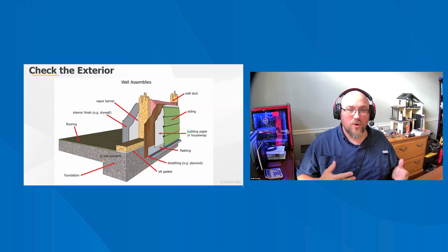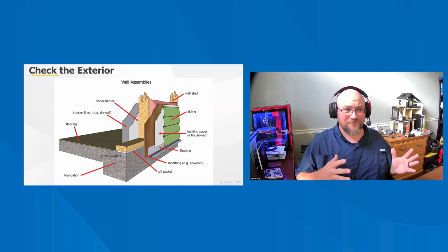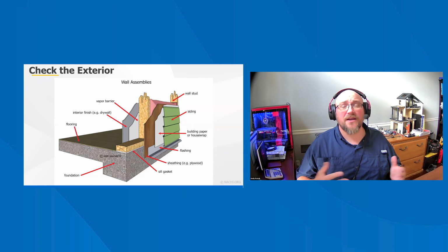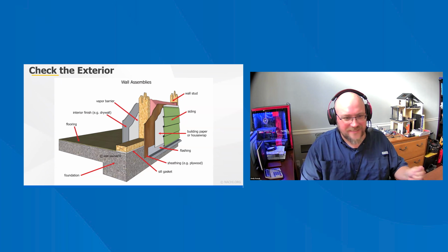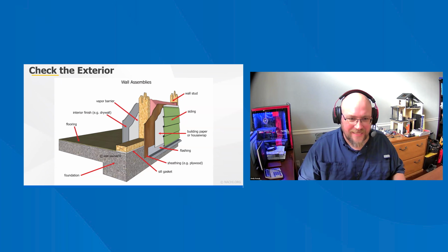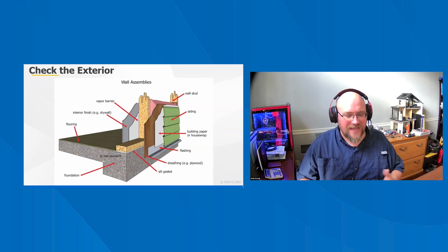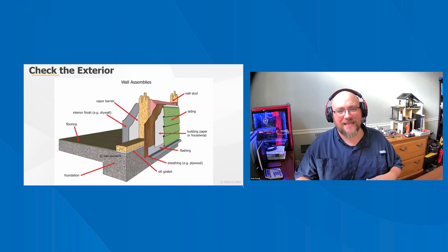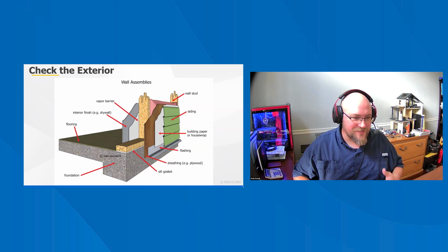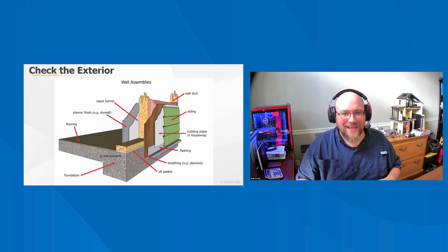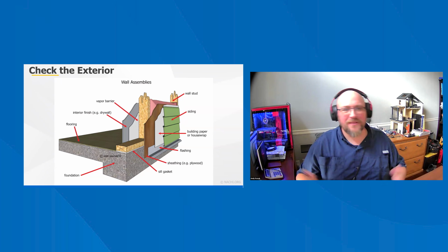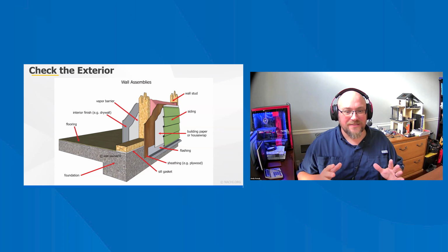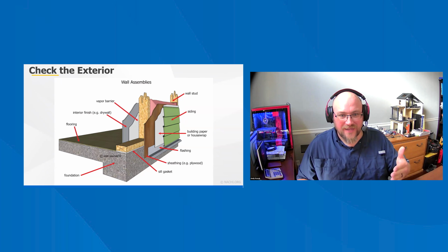And so what we're seeing a lot of in my area is a lot of water intrusion, because they're not sealing correctly. Nobody told these guys to read the installation instructions. They're not taking any training classes or anything like that. They're basically pulling people off the street and saying, "Hey, go put this up, install it," and they're not really given any direction. They're saying as long as the tape's up there, it's good. Well, it's not, because water gets in behind the siding.